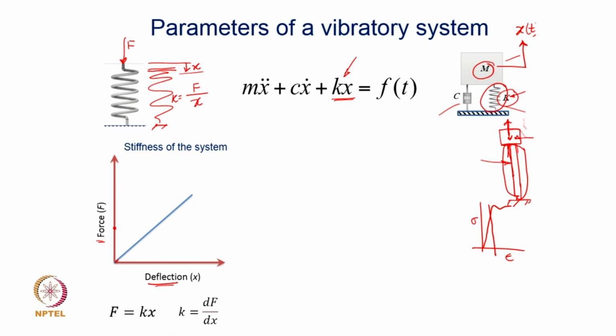So, on similar lines, if it is any mechanical structure which has a compliance, there are situations where the linear relationship deviates or is no more linear after a particular point. So, the linearity is lost, and you have a nonlinear relationship between the restoring force generated and the deflection. That means the change in the force value would not be the same for equal increments in the deflection. So, this df by dx, which is the slope of the curve between force and deflection, is continuously going to change. So, the stiffness is different here, and different here, and different here.